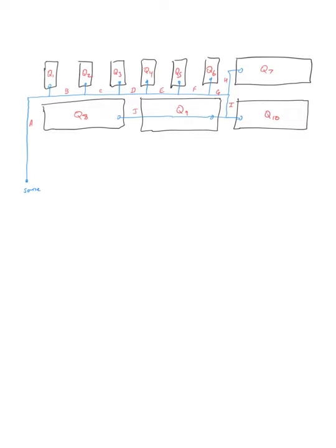And now let's say we're looking at this garden bed that is over here. Let's see, where's my laser pointer? I think it's this. All right, Q8. Okay, so we've got this garden bed here, and it needs a flow of Q8. So what is the flow rate in pipe J? Well, the flow rate in pipe J is just going to be Q8. So I'm going to write that right next to it, Q8.